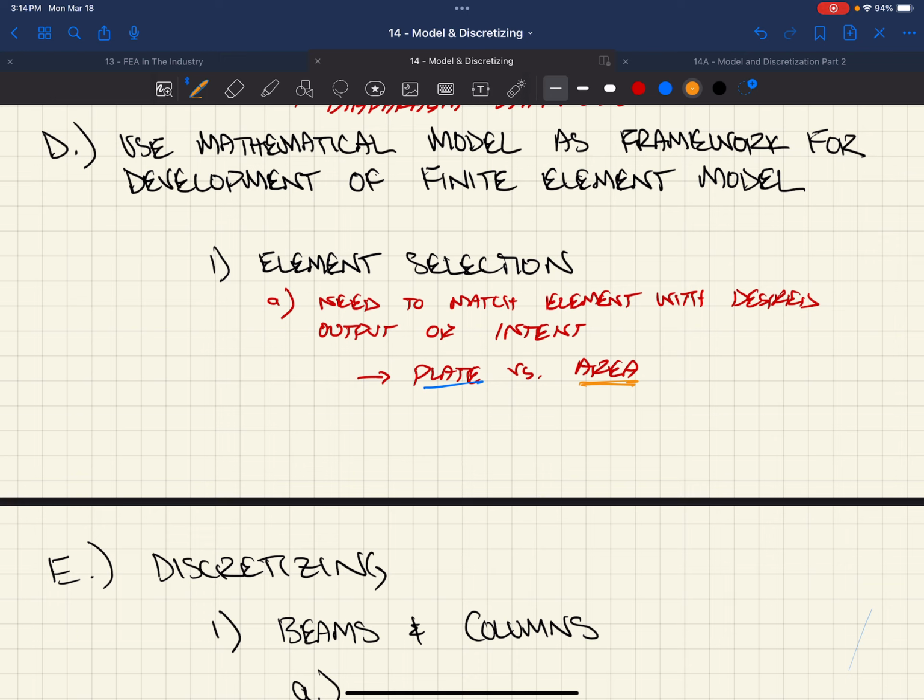And so areas are increasingly becoming the better choice or the preferred choice to design diaphragms or in-plane elements because it also allows us to auto-mesh things. And auto-meshing is incredibly valuable because we can change the mesh quantity, which allows us to check convergence easily without making sure that all of these interconnected nodes match up to interconnected elements, right? We have a vertical wall and a horizontal diaphragm, right? We need to make sure that that wall and the diaphragm are connected at nodes. And so VA will do that internally, and you can see it in its meshed configuration in the results tab.